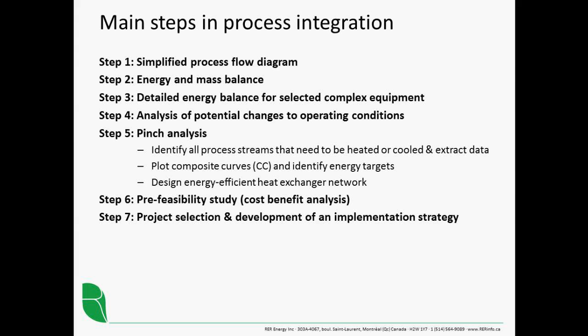And we do that detailed energy balance to better understand these complex equipment, both so that if there is a heat recovery opportunity within that equipment, we can make use of it, but also to identify any potential changes to the operating conditions that we might make that would result in more efficient plant operation or process operation. And that's step 4 of this process.